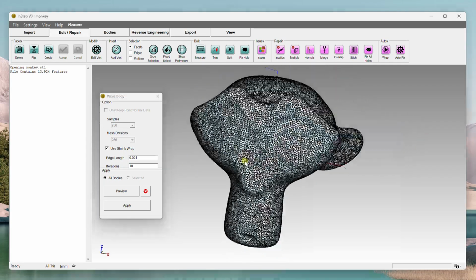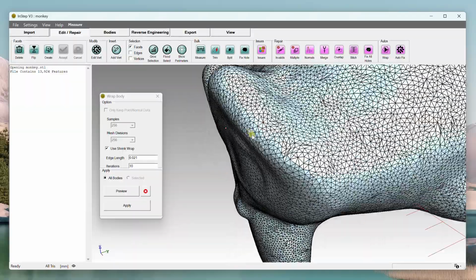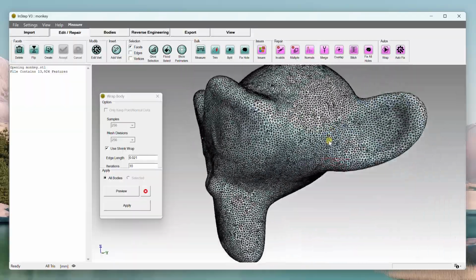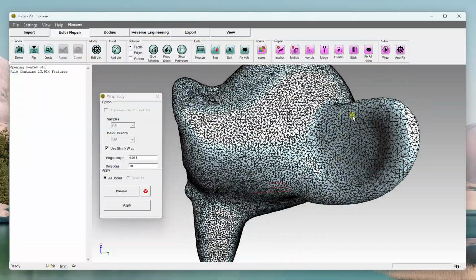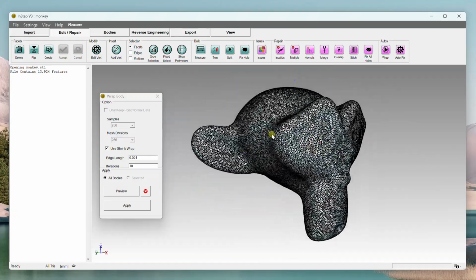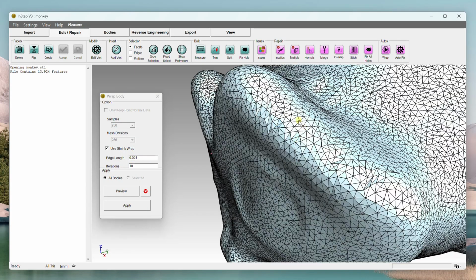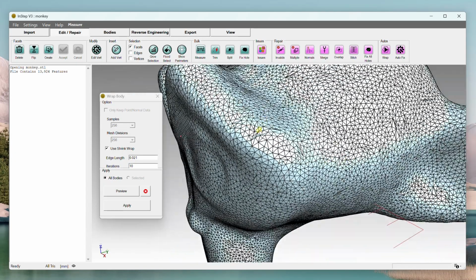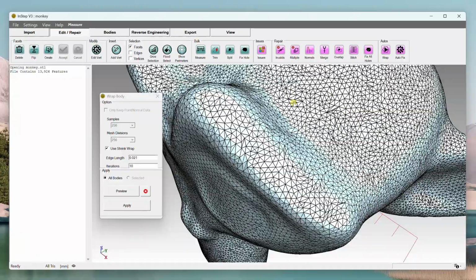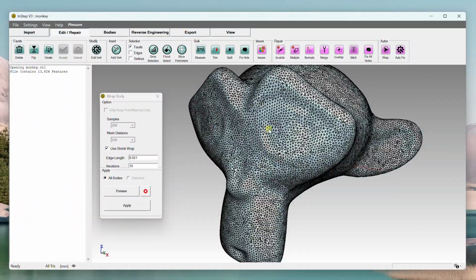So this took about 30 seconds, actually relatively quick. You can definitely tell that it's not quite down to the original body. There's still some amount of extra space that's being added to this, as if, again, it were shrink wrapped onto it. And it's given us an edge length of 0.021, and that is actually these characteristic edge lengths here. We have ways to refine this and make it cleaner for the places where it's sort of jagged, but in general this would be a suitable size.